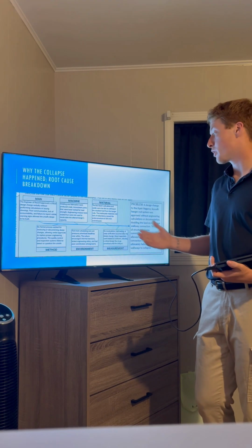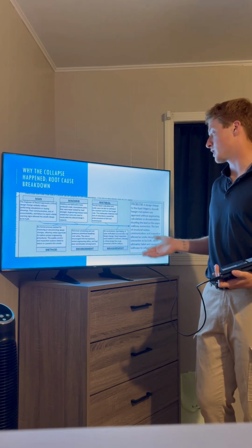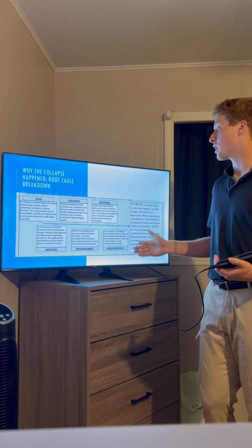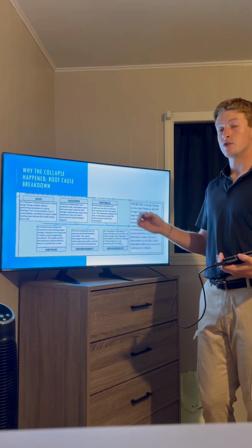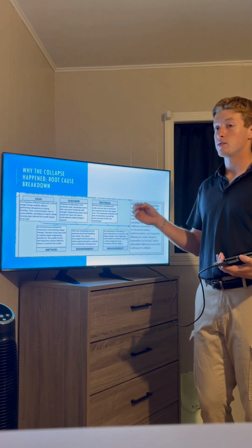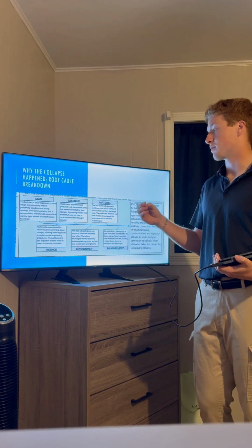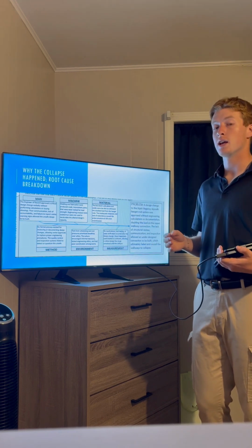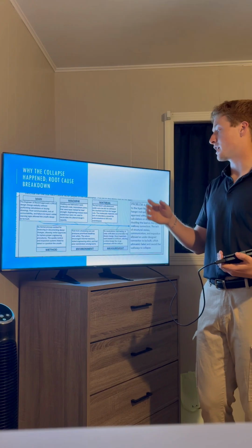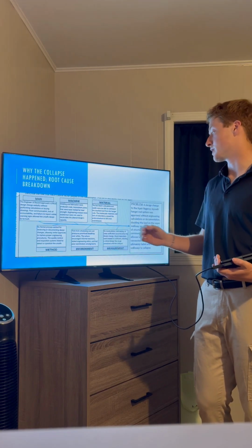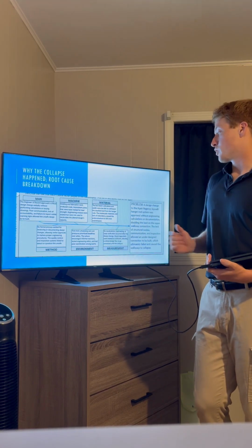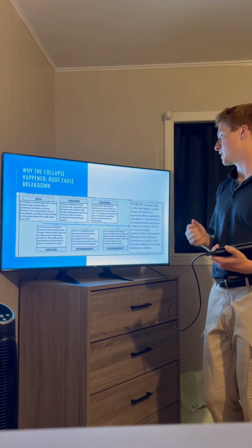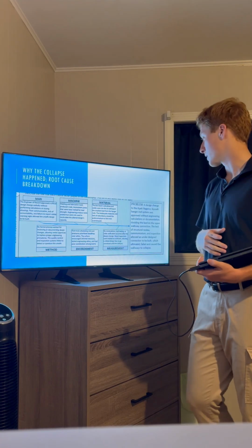For measurement, there was no recalculation, there was no load testing or code verification that occurred after the design change. How they overlooked this, I don't know. It was so simple. They could have got the proper documentation. They could have got the proper drawings. They could have got the proper materials and proper machines to build the right things. But no, they chose to overlook that and just go off the word of mouth and skip through all these things. Visual inspections were treated as sufficient, which allowed critical design flaws to go unnoticed until the collapse. And these all ultimately led to the collapse of the skywalk.